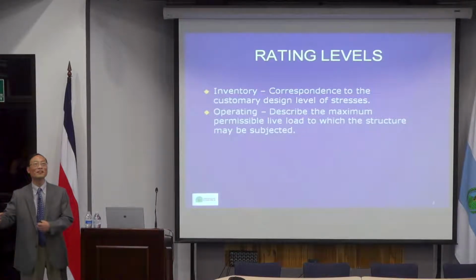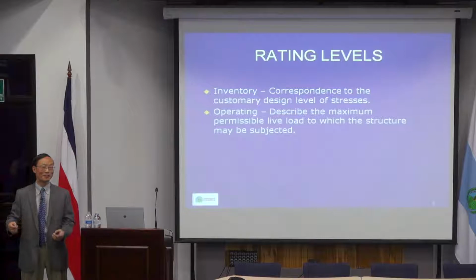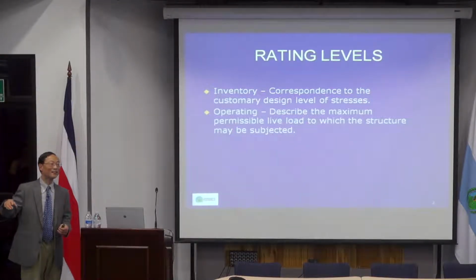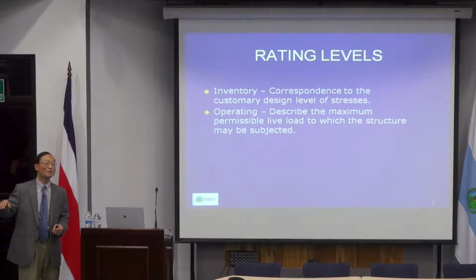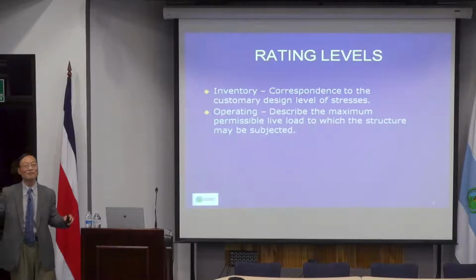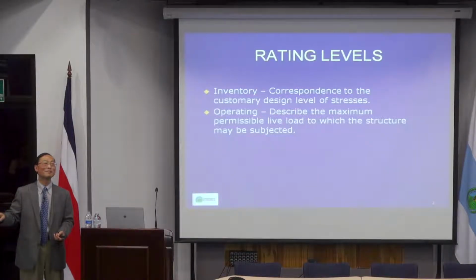Now the design code also has to accommodate. But most of these bridges have already been built, and because we know that when we build a bridge, we have bigger safety factors. And if we use the design safety factors to gauge the current bridges, then you will find probably more than half of the bridges unsafe. What we mean by unsafe is that the probability of failure is relatively high, but still very, very small.